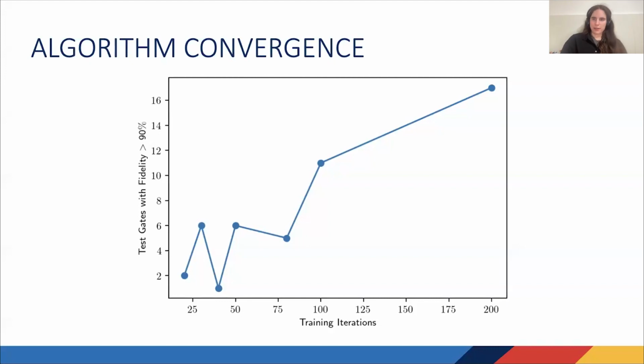So the greatest challenge I would say is the trade-off between making a faster gate and getting more leakage. Because in order to get a faster gate, you try and ramp up the amplitude of your pulse usually more quickly. So you need more power, more amplitude because it's a shorter time. You still need the same area of pi under your pulse.